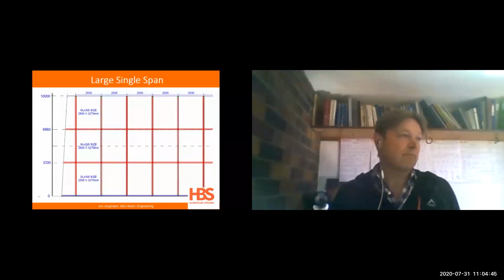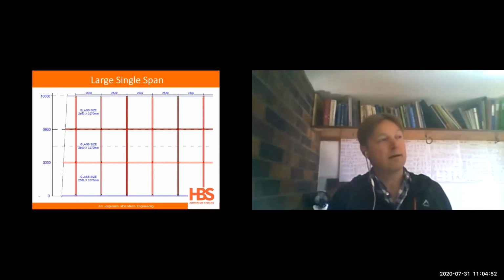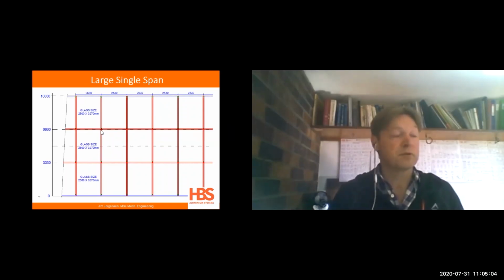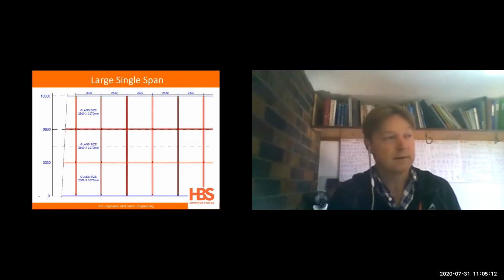So these curtain walls, you can schematically show them more or less like this. If you choose an example of 10 meters high, the red part here would basically be the steel structure that you'd have to put up with mullions and transoms in between. And on the front of that, you would essentially have the aluminium screen holding the glass. And that would be the structure of these large span curtain walls. So it could be 10 meters, it could be 12 meters, it could be 8, or whatever the size is. But that's essentially the structure that you find.